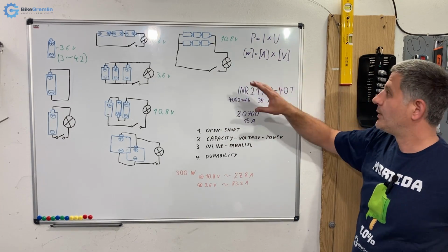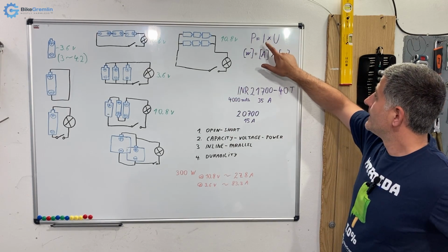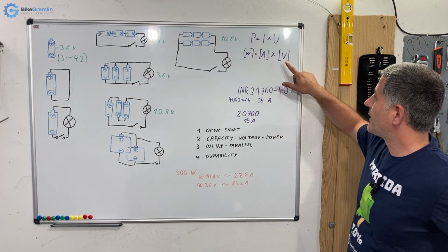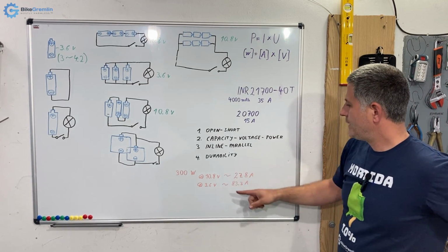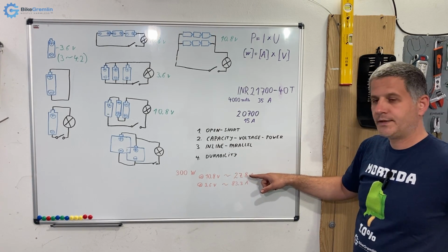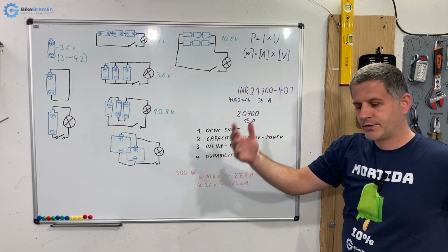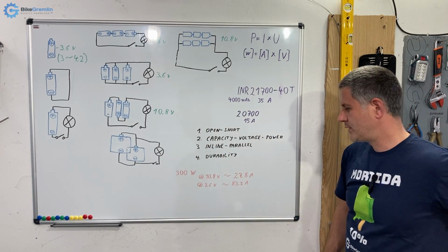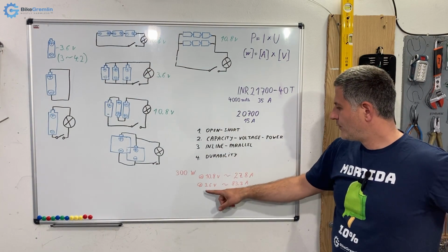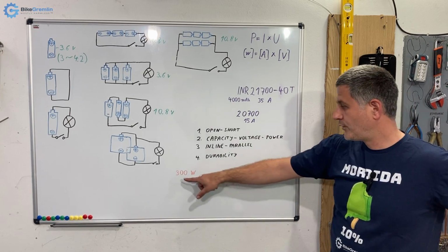and you can see my video about electricity, current and power to understand what's going on there in physical terms, but basically power equals current multiplied by voltage, or for units, watts are amperes multiplied by volts. So if we take the 10.8 volt battery, we will need just about 27.8 amperes to get 300 watts. Not considering the losses, drain and other things, it's a simplified explanation. However, if we connected batteries in parallel, then if we go with 3.6 volt voltage, we will need 83.3 amperes for 300 watts.